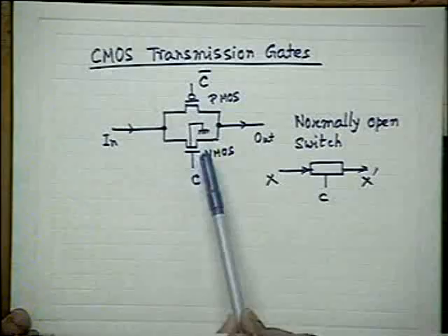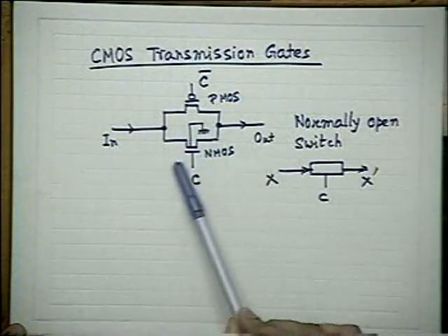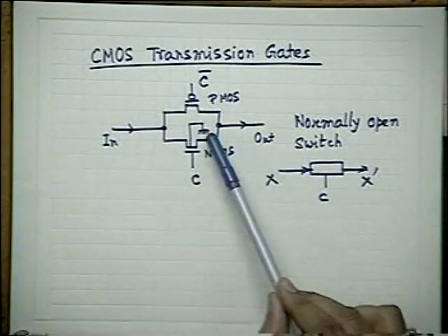But that is not permissible for bipolar transistors. Once it is designed, you cannot interchange emitter, particularly for vertical transistors. You cannot interchange emitter and collector. Please remember this. So here, this is grounded because in NWell technology, NMOS is developed on the substrate. So substrate is grounded, this is grounded.